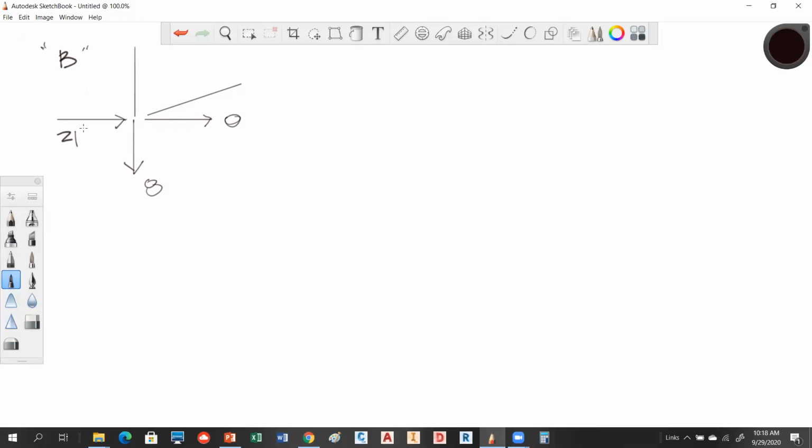All right, so now what do we think's going on with the diagonal component, BE here? This guy plus this guy, well, that's 0. So this guy's going to have to counteract the forces going this way. So compression or tension? Compression. Good. So if this guy's acting down and that guy's acting down, what does that tell us about BF? That's down, that's down, so then it's got to be up.